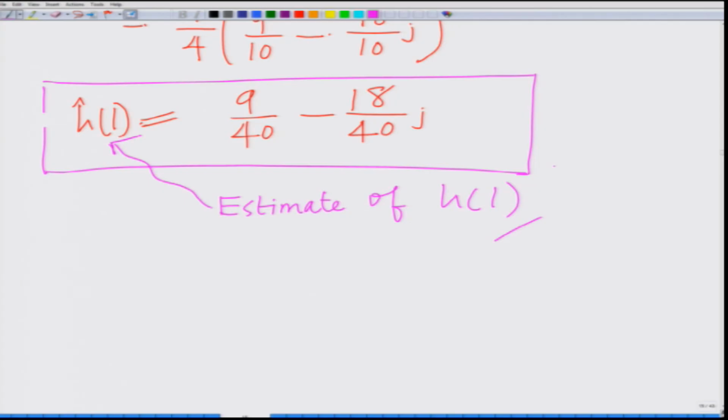In fact, if you look at this example, what we have done over this module and the previous module, we have comprehensively looked at this OFDM estimation scenario in a very thorough fashion, and it is basically a sequence of a large number of steps, and one should remember the logical ordering of these steps. Basically, you have the symbols that are loaded on the subcarriers in the frequency domain, you convert it into the time domain by taking the IFFT of the symbols loaded into the subcarriers, add the cyclic prefix, transmit them.